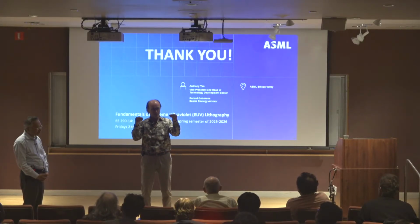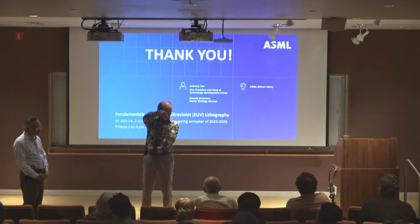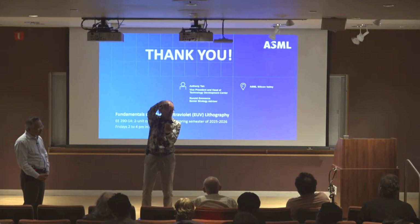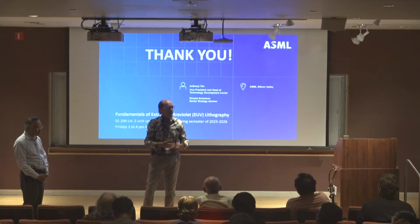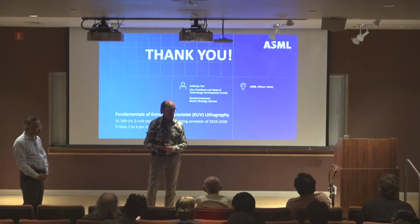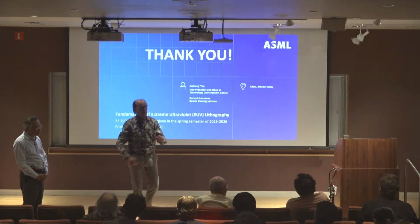Perhaps bring in these poles a little bit, regain a little bit of that contrast, and now I can also print gaps in these lines, but how small I can get that gap, that's the so-called tip-to-tip difference. That depends on how you optimize the illumination and how you optimize the OPC. So it's a very interactive discussion between us and our customers. Hope that answers your question.